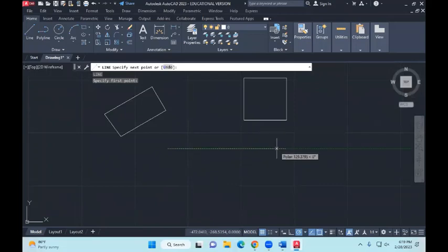So polar tracking is like assistance to you while you are drawing. At most of the times, you would by default have that turned on, to assist you while drawing. So once you know the angle, if you know what distance the line has to be, then you can just enter the distance while the angle is already set in place.